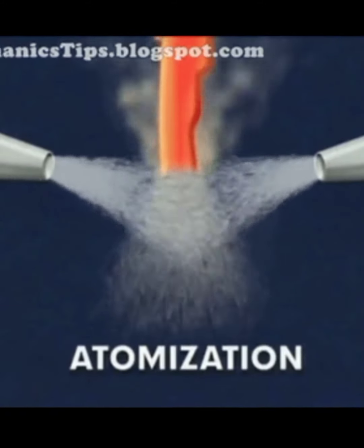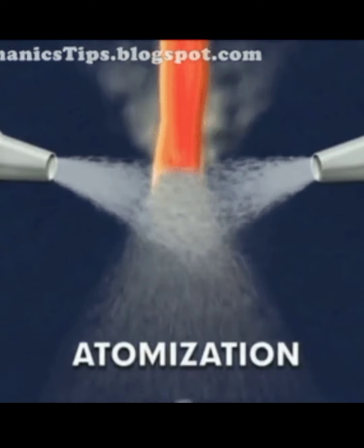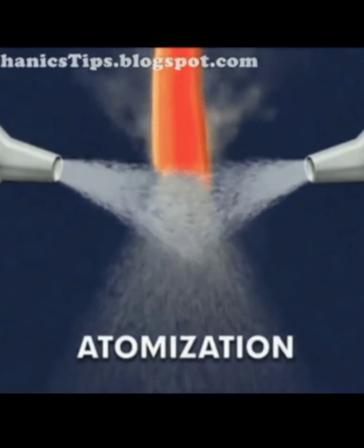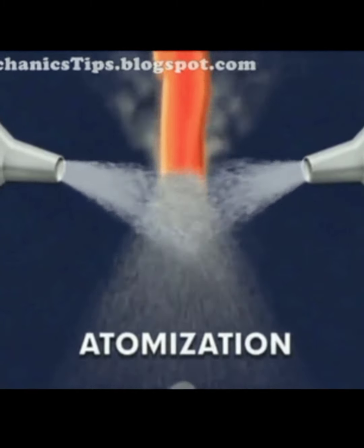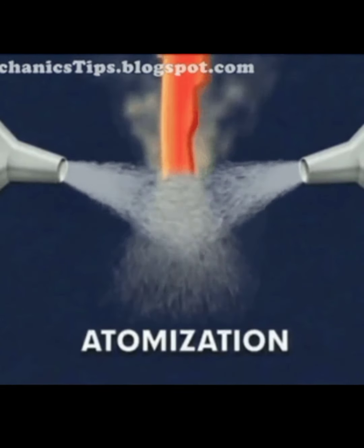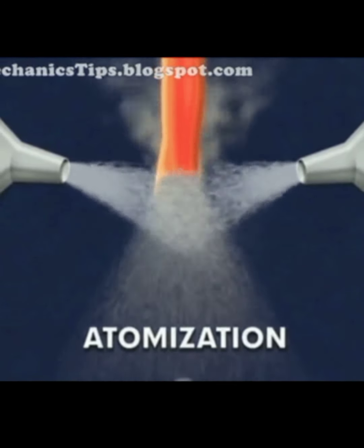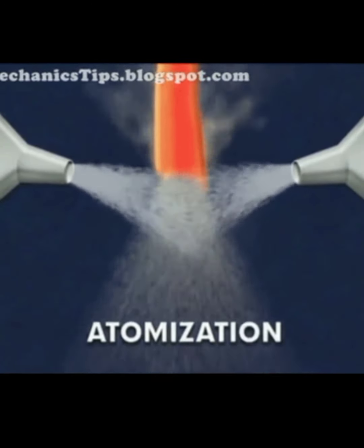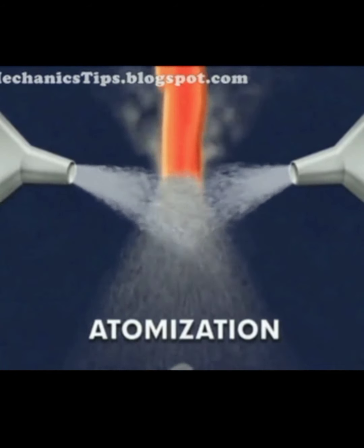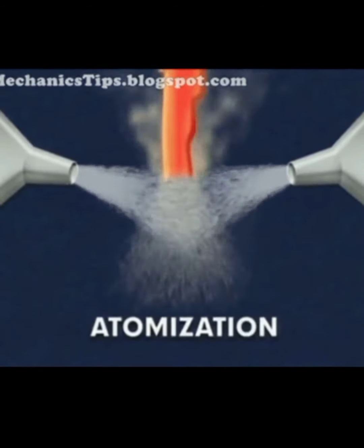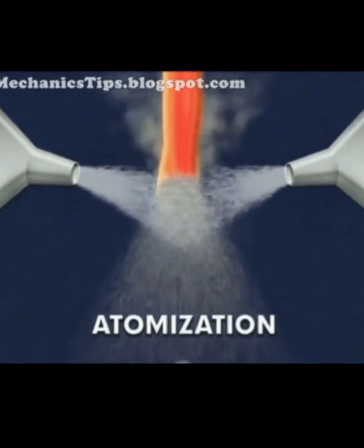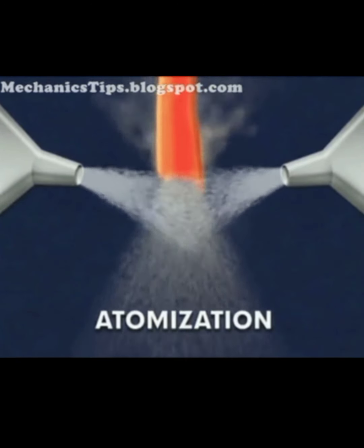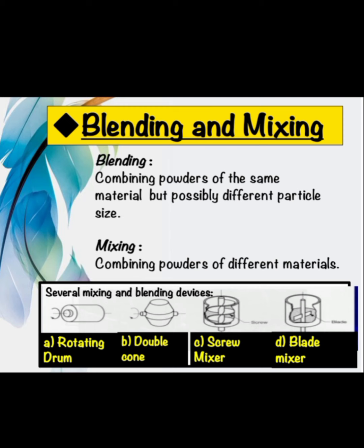We can see the animation of atomization in this. The molten metal falls down from some height. We have very fast blowers or sprayers that project a strong jet of wind. Then what happens? Very small particles are blown by the air, and we have a cool plate there. When the particles travel, they condense on the plate, and then the particles are cooled down. We have a vibrator attached which periodically vibrates the plate, and the molten metal is atomized by using the air.